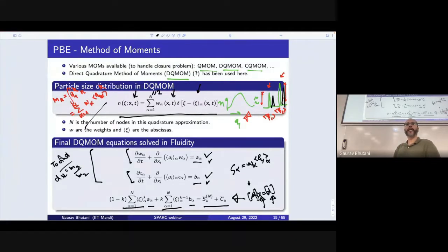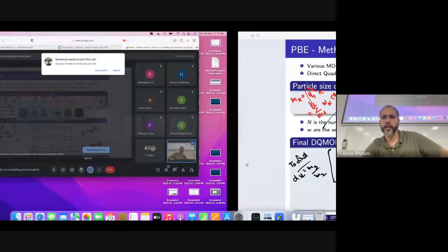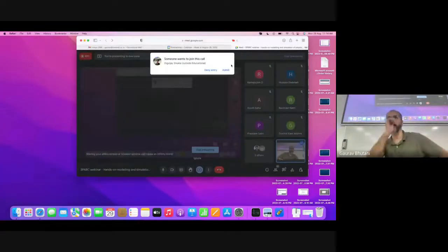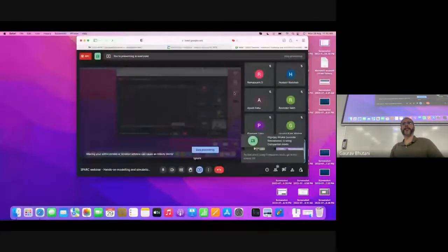If you simply want to find the overall amount of flow that happens, you don't really need to solve this. But if you need to solve the flow fields, then it may be of interest. But then again, you have to see whether these rock particles, when they fall down a distance of, let's say, 5 meters, not very high, that 5 meter fall may not be a strong function of the interaction with air. But if it's falling over 100 meters, then after some time it may reach a terminal velocity. So then that drag of the rock particle with air has a significant effect, right?